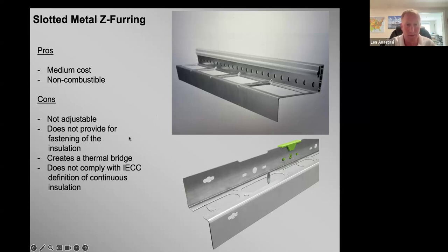Medium cost, non-combustible. There is no adjustability. It doesn't provide for the mechanical fastening of the insulation. It creates a thermal bridge. I don't think that either of these comply with the IECC definition of continuous insulation.